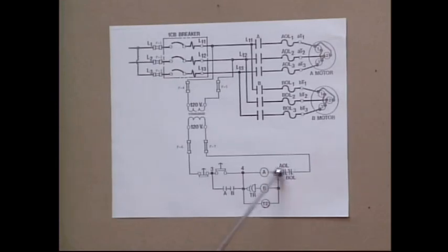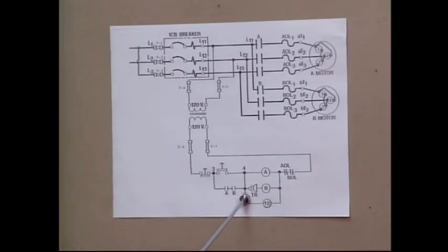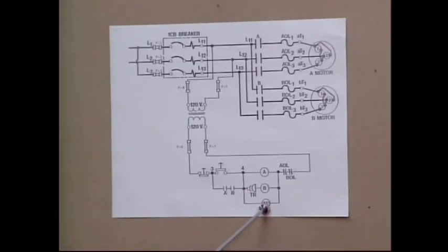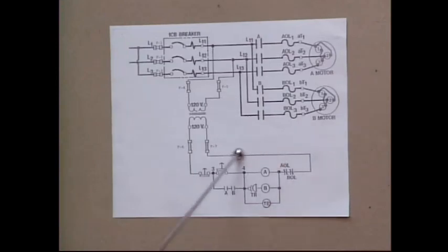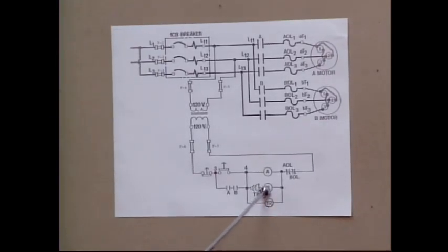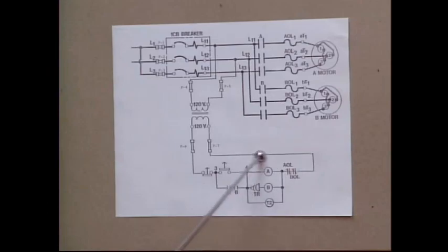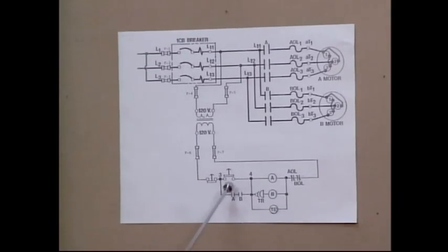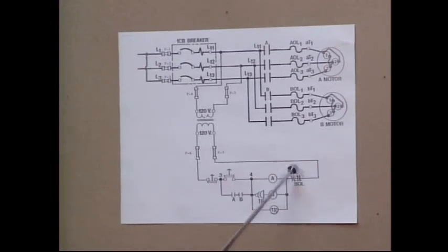A appeared not to be energized at all, but B did go. Now, for B to operate, the TR coil must be energized, have its path. The TR contacts, the mercury tube for the TR coil must time out and close, and then B get power. It has to have a circuit back to X2, and then go. Now, that part's working. B contactor closed. The part that's not working is between the start switch and A, or possibly from A to AOL. Let's check those parts.